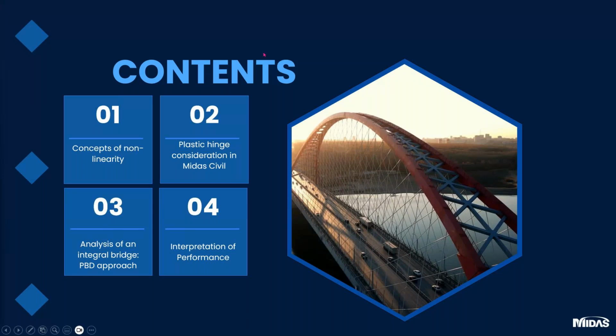So, the contents of today's presentation will touch upon the nonlinearity concepts. Then we will look into the plastic hinge considerations and application in MIDAS Civil. Then we will continue with our previous problem with respect to the integral bridge. So we dealt with the response spectrum analysis to compute the demand. Now for the capacity, we will carry out a pushover analysis onto the structure to interpret its performance.